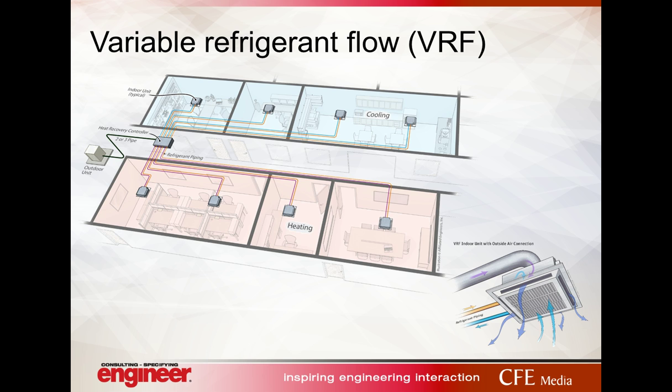Now, VRF systems are something we don't see a whole lot in healthcare applications, but there's not really necessarily any code requirement that precludes them from it. There's a lot of similarities between VRF systems and water source heat pump systems and the way that they're applied. Both of them are somewhat zone-based systems where you could serve one individual space or maybe a cluster of spaces with a single system. You can see the picture really depicts that each individual space here is served by one VRF indoor unit, but they do make ducted units that could be used to serve multiples of those at the same time.